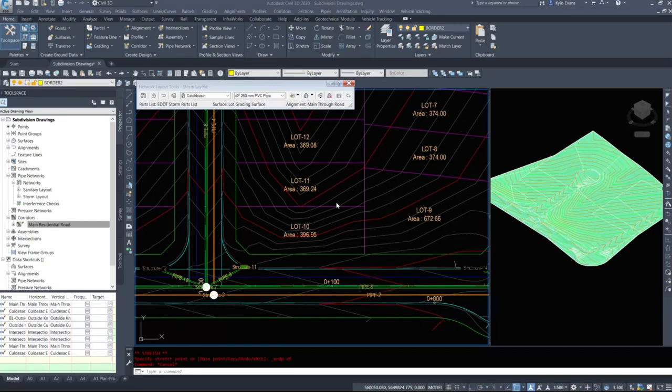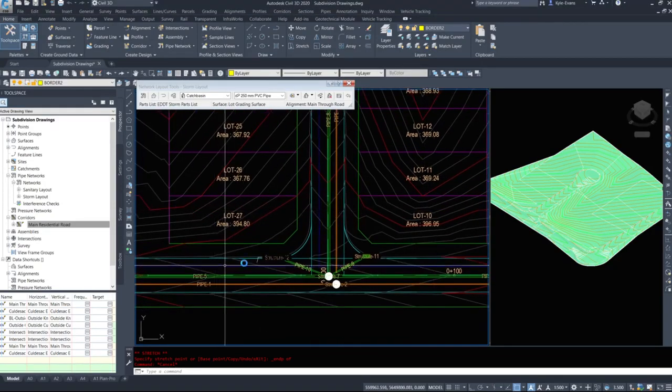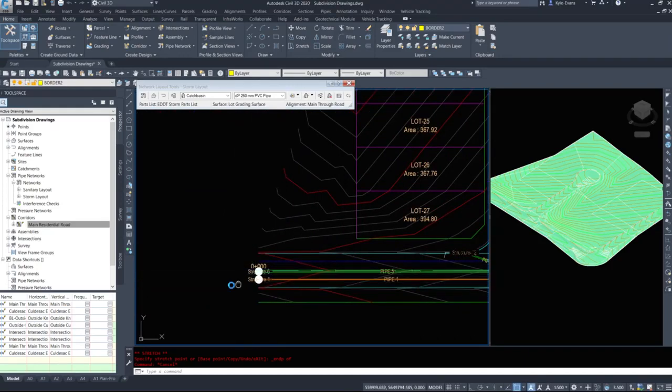In the next part of our subdivision design here, we're going to work on sloping the underground utilities. Once you have the sizes, you can figure out slopes and manhole drops and what's needed to have everything flow properly, but we're not going to worry about sizing the underground utilities. We're just going to go with what we have, and we're going to start from the bottom and work our way to the top as we slope these based on the tie-in.